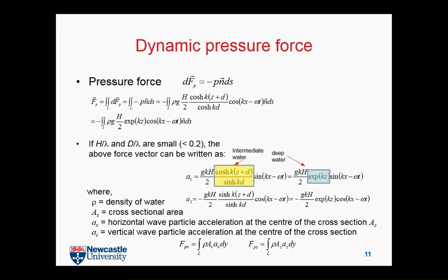Here is the reason why you can see the expression here for integration. That is pressure. We have rho, we have g, we have h, we have 2, we have this term, we have our cosine function. And then here is the pressure for one point, and then if you do an integration for the whole surface, we will have the total pressure from water, from wave.